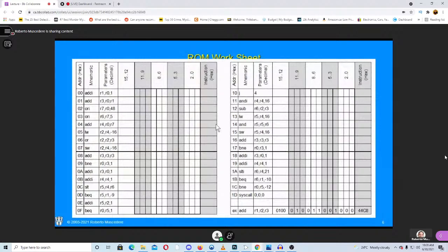If it doesn't work, it's either the hardware or the software. But if you've done assignment 4 and that one works, and you scale it up correctly, then it will likely be a software problem. And if it's giving you an issue, just trace it one line at a time. Run the first instruction, check the value in the register, and say, did R1 go to 1? Okay, run the next one. Did R3 go to 1? Then run the next one. Did R7 go to 48? Run the next one. Is R6 48 ORed with 5, for example? And if you see all these things are working, then find the instruction that doesn't work, and that's what the problem is. There's not really a better way to do that.